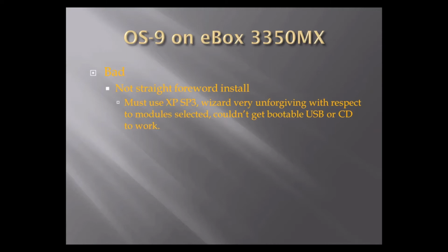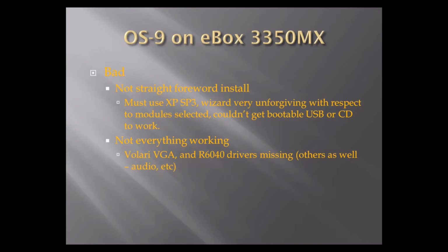Also, I couldn't get a bootable USB or a bootable CD to work. That would have aided the process considerably, and that's why I had to use the small module that converts an SD card to an IDE hard drive. With the basic install, not everything's working. The Volari VGA and the R6040 drivers are missing.